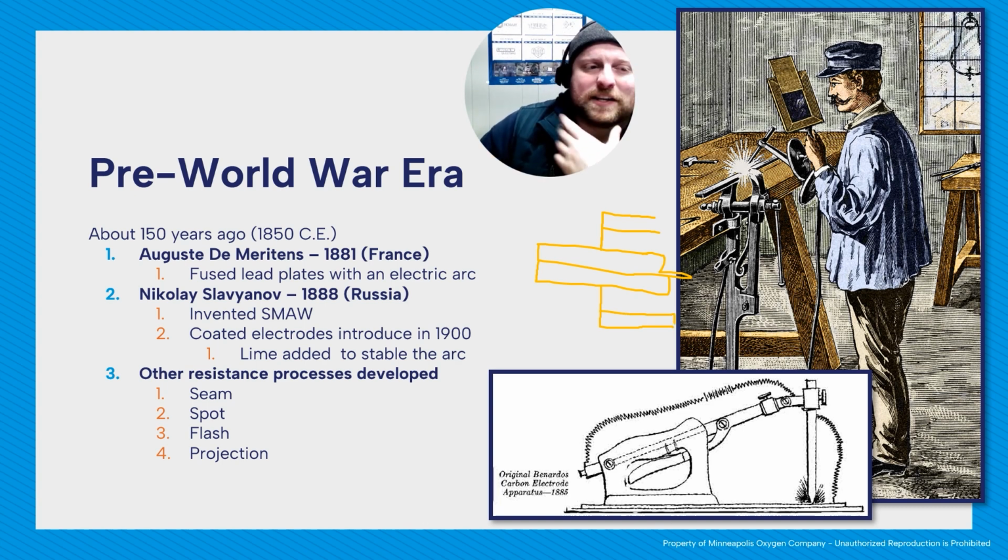And basically with resistance welding, where there's resistance in this connection, which is usually where these 2 plates meet, that's where the current will start to melt, and then from out there we'll melt and actually make our weld. So that's the main difference if you see resistance versus arc welding. Arc, we're using electric arc. Resistance, we're using basically electric current.